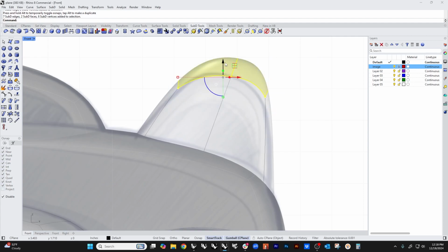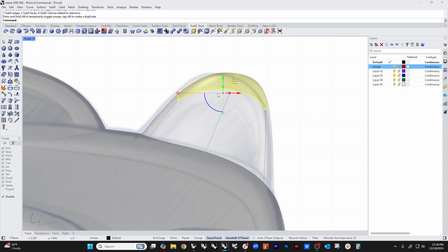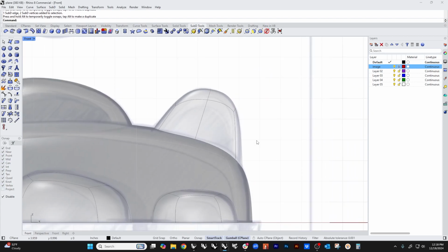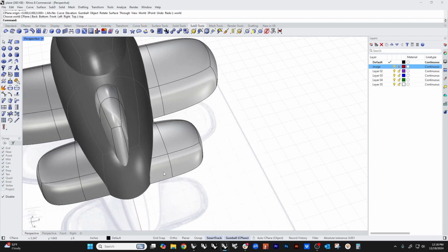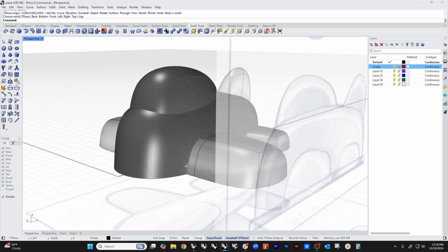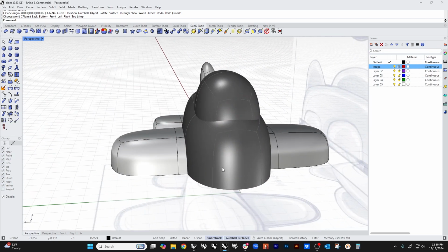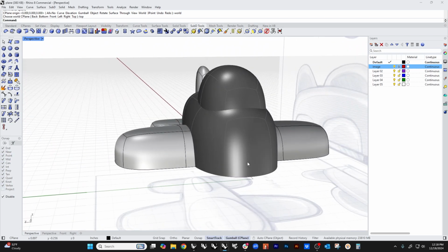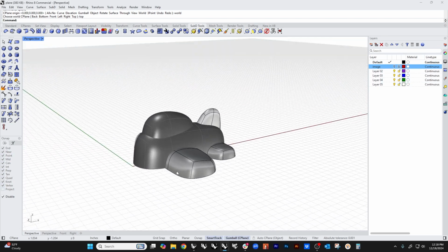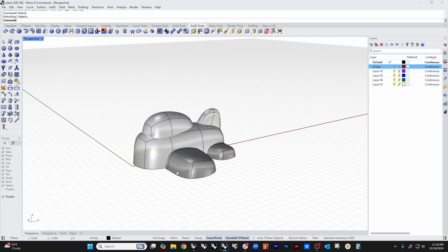And then we're going to grab this entire thing. Again, just Control-Shift-Click, Control-Shift-Drag to get the selection of these sub-object elements. And we're just going to pull this around until it does what we want it to do. Okay? So in just a couple minutes, we put this together and we've got the basic layout for what we need to do with our plane. Now, I'm going to hide my images because I don't need them anymore. I'm going to unlock everything.